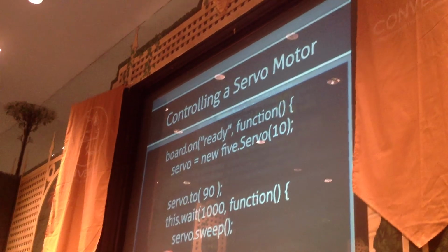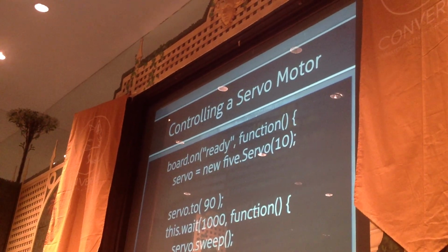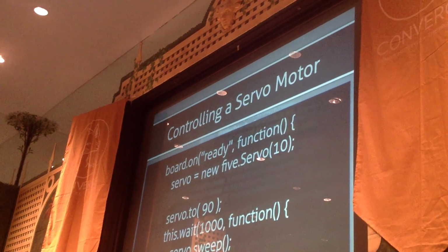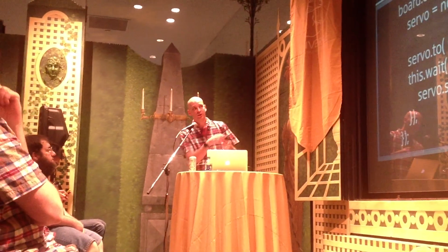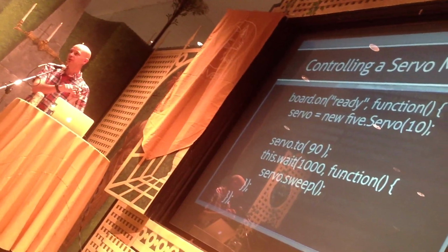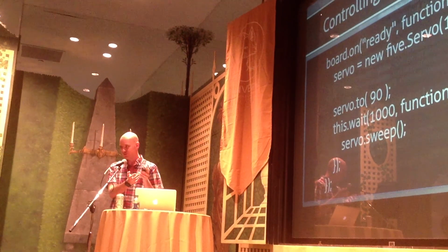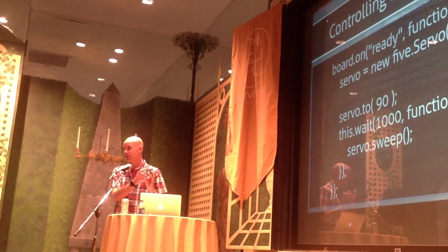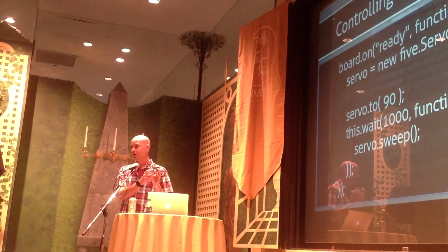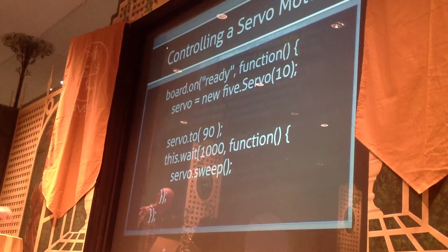So the servos themselves, let me disconnect this LED. You have all your digital pins over here. You have a power ground, your 5 volt over here. So 5 volts would typically run electronics like this. So you have three wires coming out of a servo motor. You have one for power, one for ground, and one for control, which is to the digital pin. You connect the power to 5 volts. You connect the ground to ground. And then you connect your controller to whatever digital pin you want over here. So in this case, it's 10, or it would be 10.